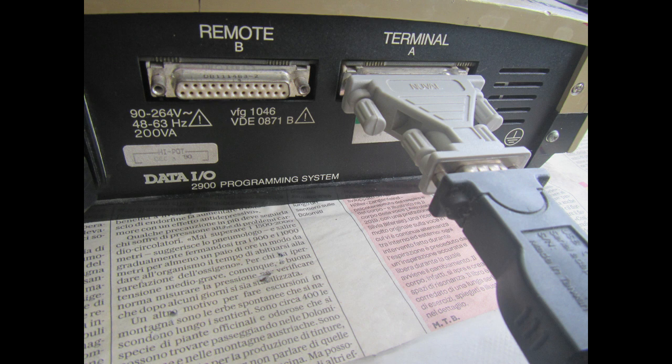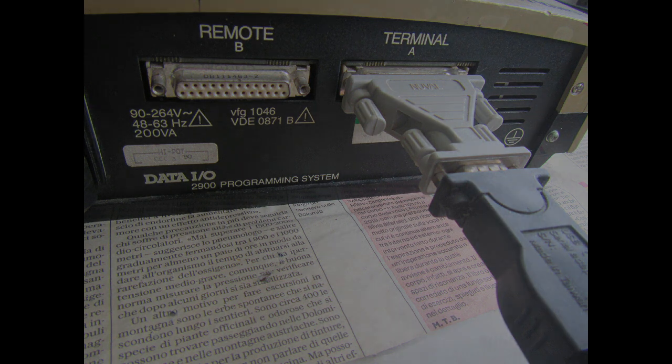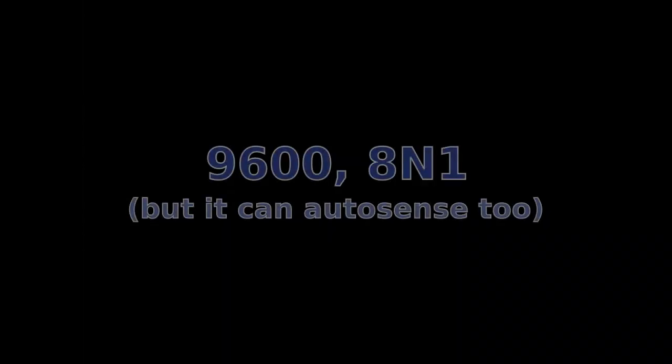Then the programmer must be connected from the port labeled Terminal A to a computer running a serial terminal emulator program. I'm using Minicom on my Linux laptop. I have used a serial to USB adapter. The serial port on this programmer has an auto-sensing pinout, so you can use either a straight-through cable or a null modem one. Serial communication parameters default to 9600 bits per second, 8 data bits, no parity, and 1 stop bit.